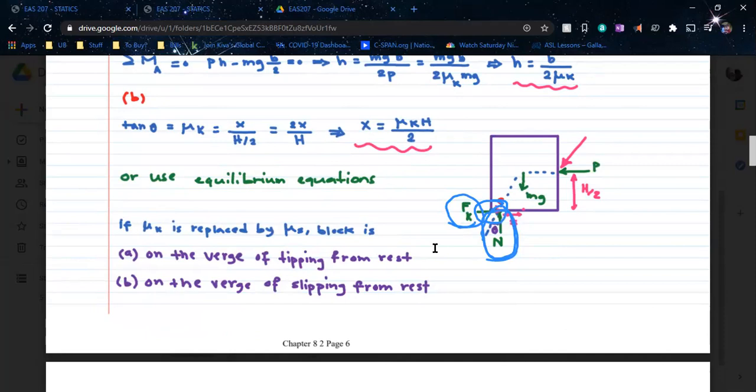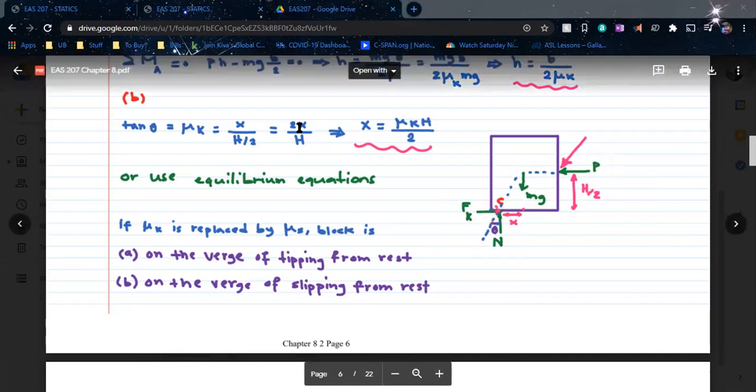So if we take the moment about that point, down in that lower left-hand corner, there's really only two forces that we need to worry about: the weight of the block itself and the applied force. In our case, that's the weight of the block and then the tension. So those are the two scenarios we're looking at.